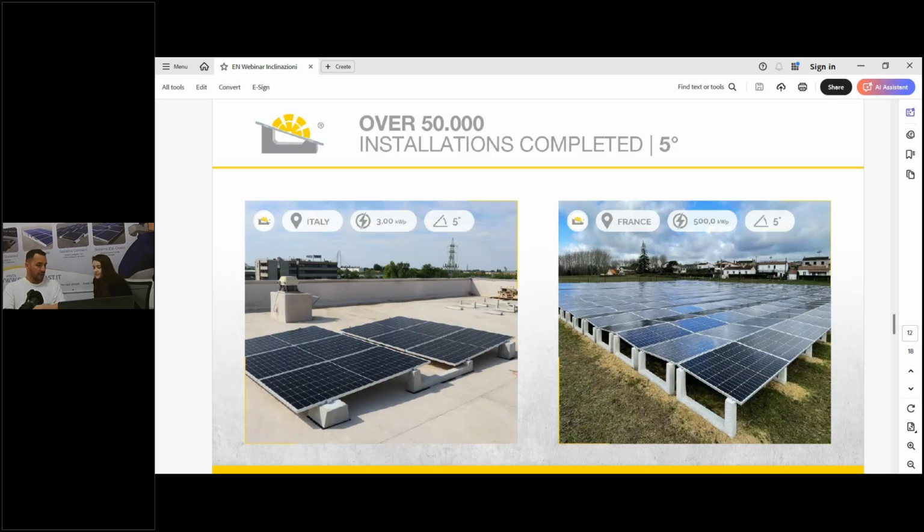Yeah, being a ground installation, in order to avoid the growing of the... Yeah, that's not the only reason. Actually, there are several reasons why they want high inclination: the grass growing, or sometimes the ballast. Like you said, if the ground is not prepared well, sometimes there might be issues with the movement of the ground. So we always suggest using some type of fabric under it, covered with gravel. Some of them even cover it with concrete, right? Yeah, which not all of them prefer, but if it's in an area where it doesn't damage.